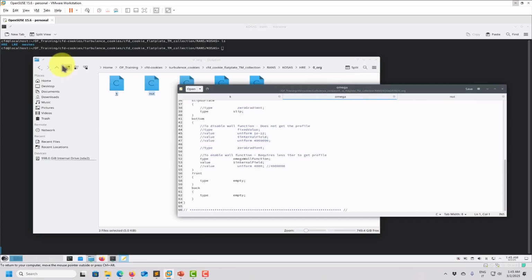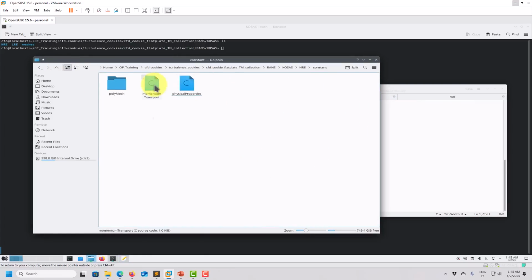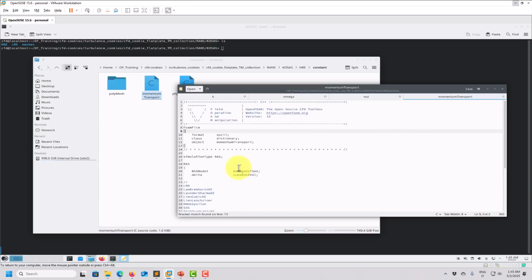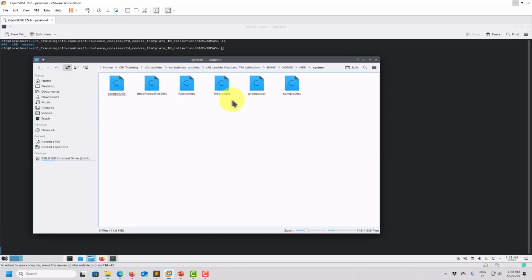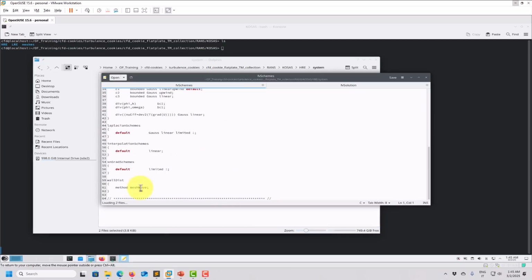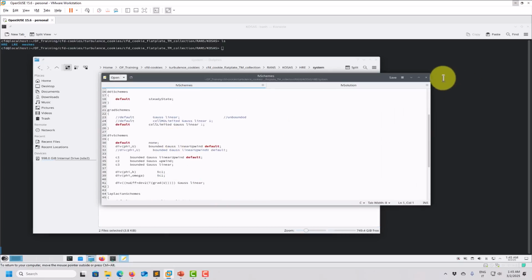Okay, and then important, let me go in constant when you choose the model. So here model transport, so you choose the model, but then you need to give this delta. Now this is a quantity to filter and so on, so you need to give this quantity. This is just for scale resolving stuff, but you need to define that, and that's all. For the rest, you go also to numerics, nothing changed. Okay, so as this is based on the K-Omega SST, you need to define the patch wall distance, but there you go.